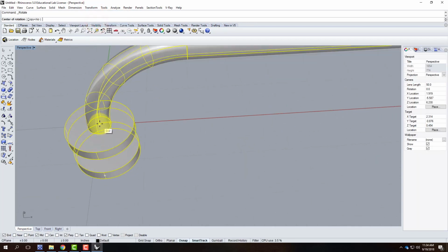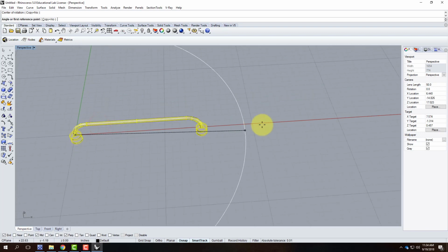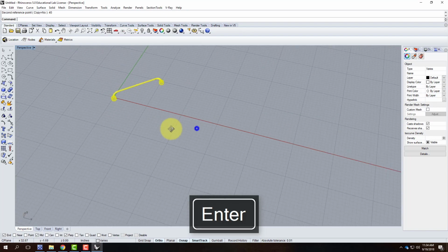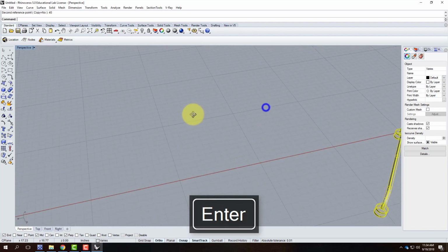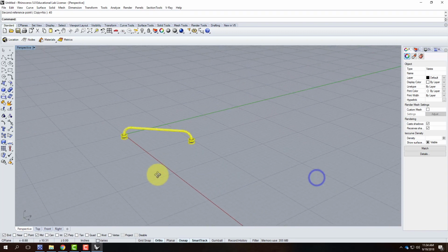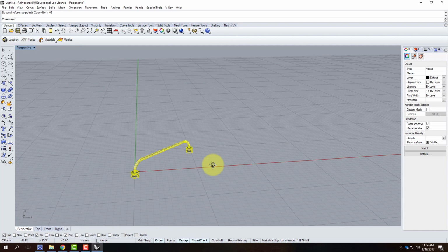I'm going to start right there at 0,0, and I'm going to rotate. I could turn on ortho here, and I need to specify that this needs to be halfway. So in that case, this is 90 degrees. It would be 45, so I can type in 45 and hit enter, and it's going to rotate it at exactly 45 degrees. Now I've set this thing up so that it lands right on a 1 foot square. So it's looking exactly as it should.